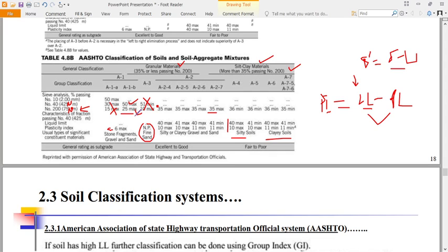So what about material A now? Let's go to material A. Material A, we have determined that it's a so-defined good material. So what matters is the PI and the liquid limit. Is that okay? The PI and the liquid limit. So this is a condition, the minimum, which this one passes. Remember it is 88 passing. This is 36. Remember it is 88 passing. They all pass, so it is enough for all these ones to pass.